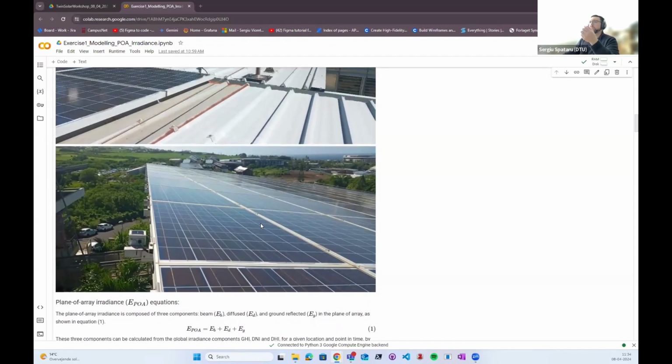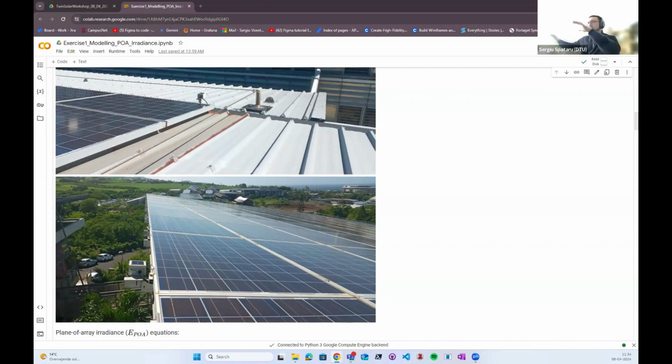Now, these are very nice and they are useful for getting the input energy of the panel. The only disadvantage is getting from plane of array irradiance at some orientation to another orientation is difficult and is not very accurate. So you can only use these measurements for this plane of array.